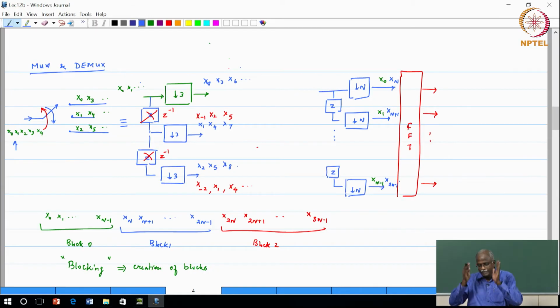So, every tick of the clock, one vector comes to the input, you compute the FFT and then you push it out. From a software point of view, this is fine. We can just index it and compute the FFT, but from a hardware implementation point of view, this would be a very good way for us to visualize and also implement the downsampler.